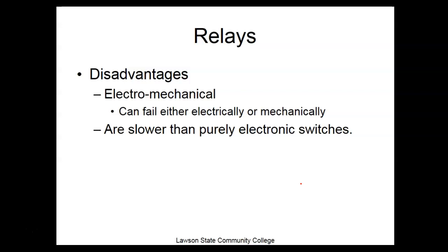My air conditioner, my heater just went out, and it was the relay. Relays are electromechanical devices. My heat wouldn't work because the blower motor wouldn't come on. The gas would cut on and everything would work, but the blower that actually blew it through the house would not work. And it was the relay.